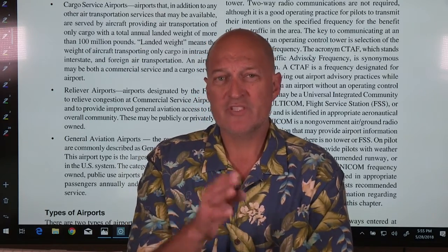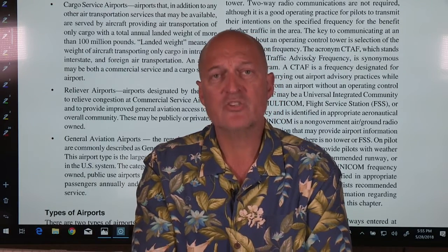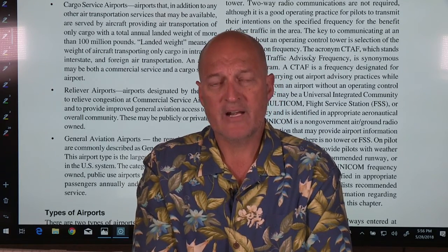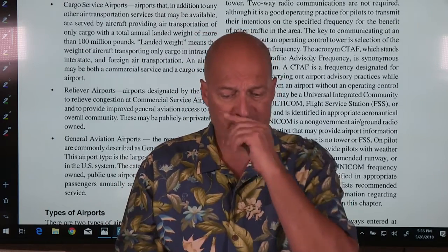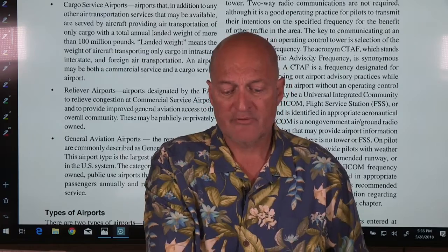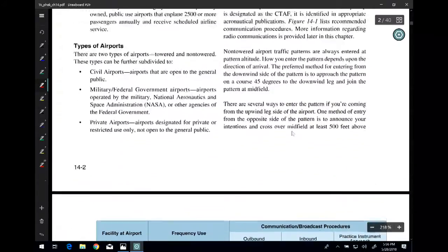So that's how you do the self-announce. You begin with the name of the airport that you're flying to, and you end with the name of that airport. That's one of the ways that we do it, especially when there are several airports very close together on that frequency.